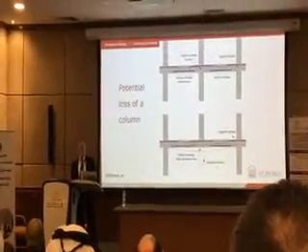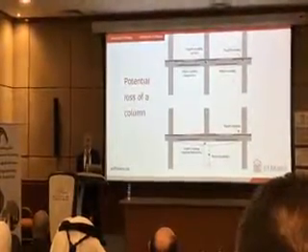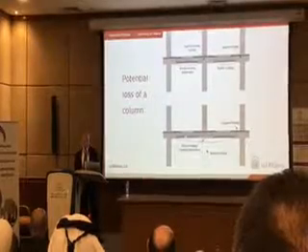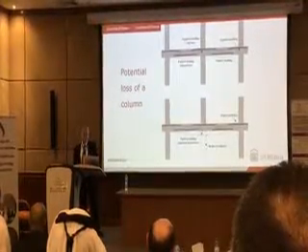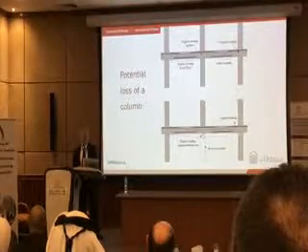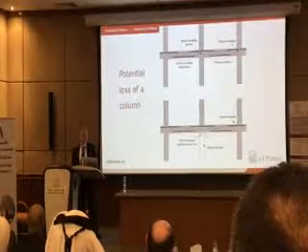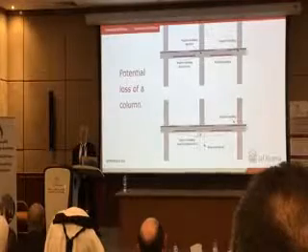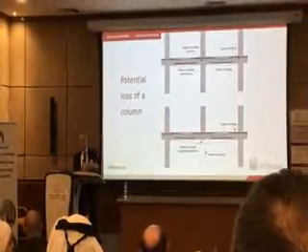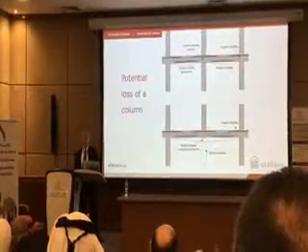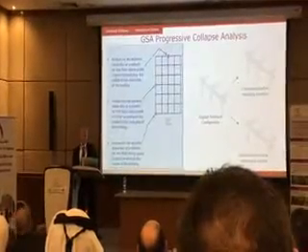But if you remove this column by loss, then of course you have positive moment for which you did not provide reinforcement, so then the whole thing may come down. So what we do is we provide integrity steel, so even if the negative moment region develops positive moment, it remains intact, and there are also retrofit techniques for that.